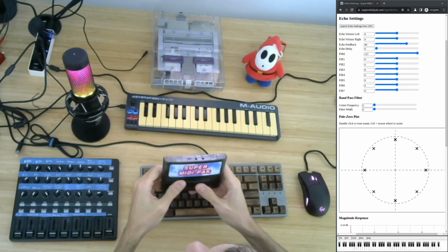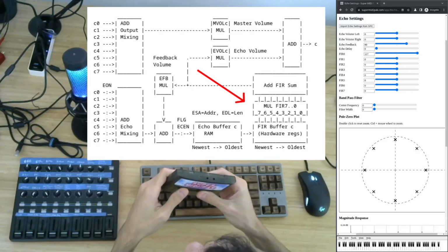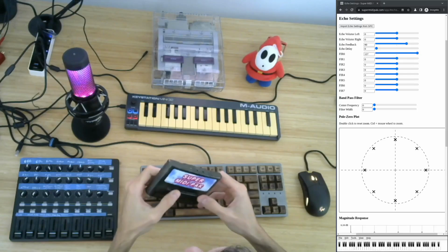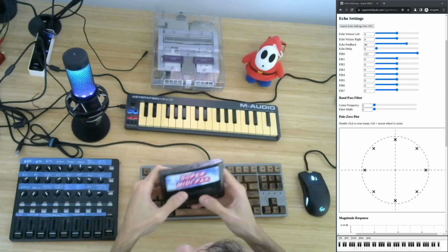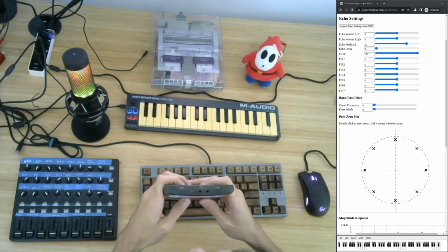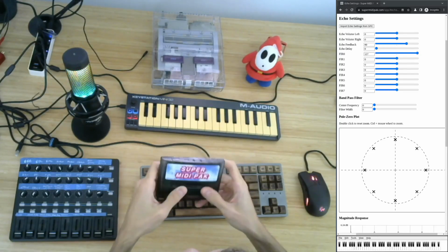Ever since I started playing around with making SNES music, I was always intrigued by the FIR filter in the echo section of the SNES's audio hardware. Unless you have experience in digital signal processing, figuring out what values to use for each of the FIR registers was a total black box. Most of the games in the SNES library make very simple use of this aspect of the audio hardware, mostly using it for a standard echo sound, so there weren't many examples on more advanced usage.